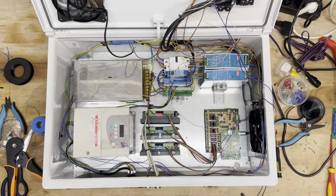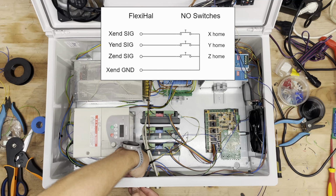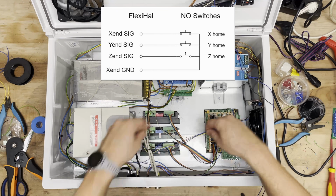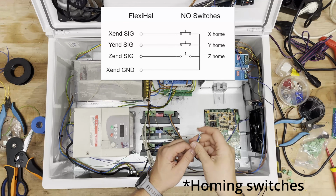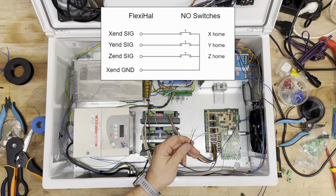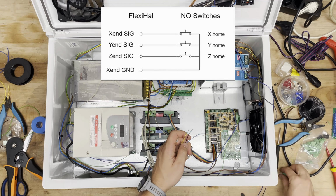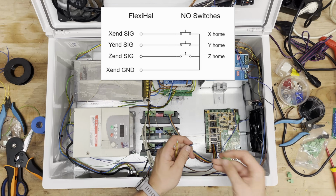Next in are the inputs, and I will start with the end stops. All end stops share common ground up into the machine, so that's why I only have 4 wires, so one common ground and then for all 3 axes each one.